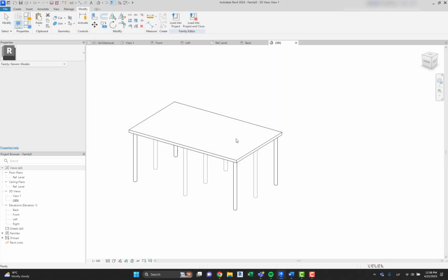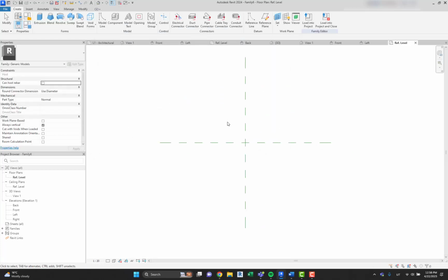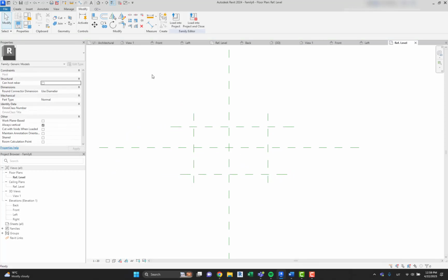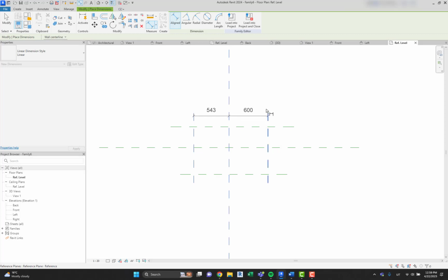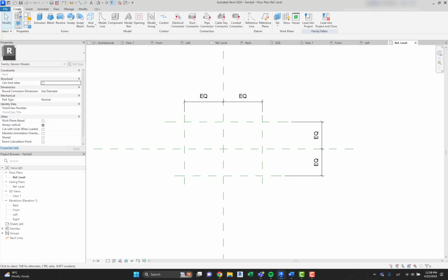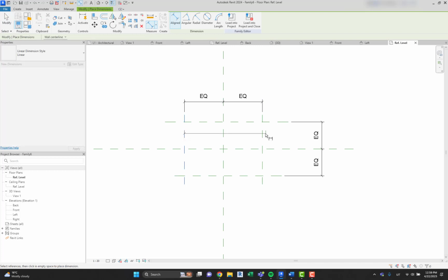And I'm going to create a plain simple chair. But of course, I'm going to use reference planes again. This is crucial for creating parametric families. So don't forget that. I hope I will get into your minds to never lose this idea to always begin with the reference planes. Okay, so we can add width, depth.